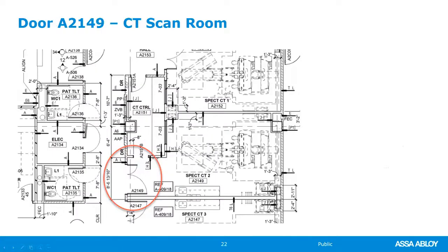Okay, so we don't have to worry about locking these doors. They're within the secured perimeter. They are an unequal leaf pair. This door does swing against the wall. This door leaf could also, well, sort of kind of swings against the wall, although there's a cased open frame right there. But it's non-rated, but it is lead lined.